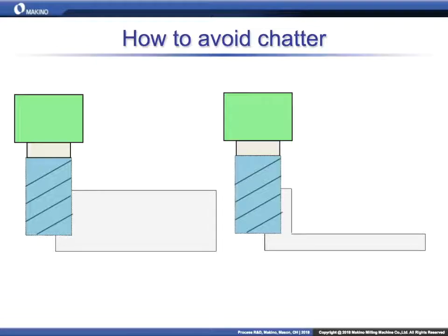Instead of selecting a spindle speed to match the vibration of your tool, the tool is not really what's moving around that much. The tool is vibrating, as we said, nothing's rigid, but it's really that wall that's doing most of the moving around. So what you want to do is measure the dynamics of that wall, the part, and select spindle speeds that coincide with the wall's natural frequency.